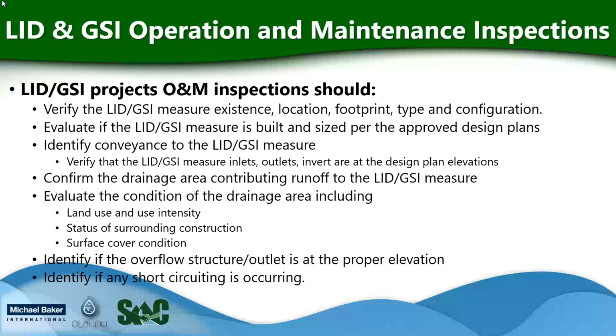Should also confirm the drainage area contributing runoff to the LID and GSI measure, and evaluate the condition of the drainage area, including land use and intensity, status of surrounding construction, and surface cover condition. Again, we want to make sure that the drainage area is stabilized. We want to identify if the overflow structure and outlet is at the proper elevation, and if any short circuiting is occurring within the system.